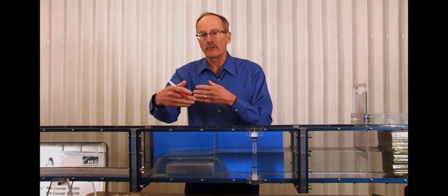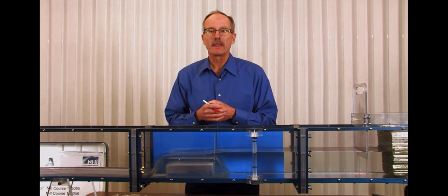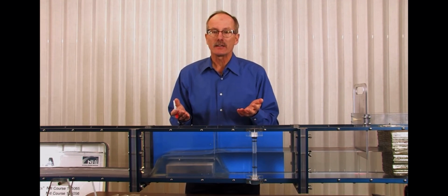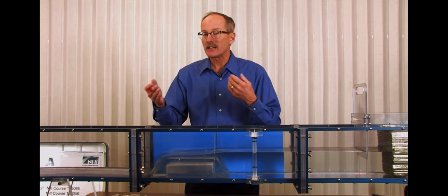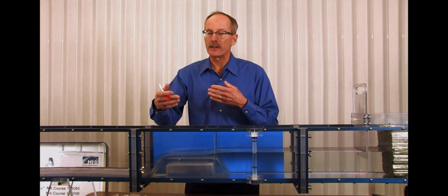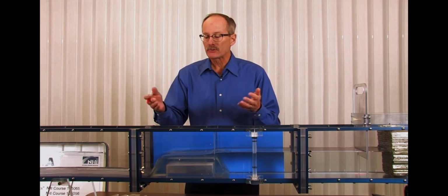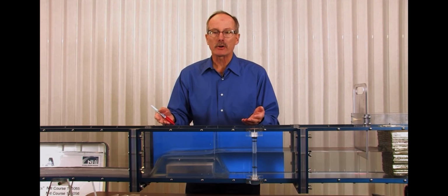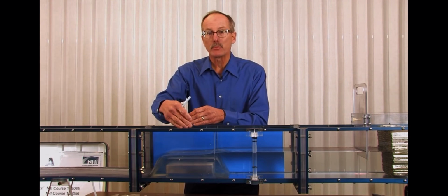It's the width or the length of that weir crest that we're looking for in that equation. The way I keep that straight is if we had a 1-foot weir and a 10-foot weir, the 10-foot weir crest would clearly be passing quite a bit more flow. So in the flume, my weir crest would be 6 inches or 0.5 feet.